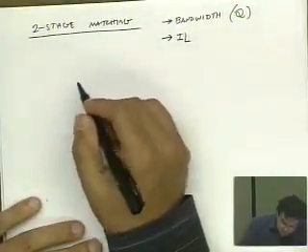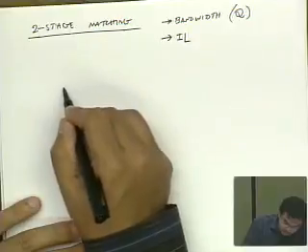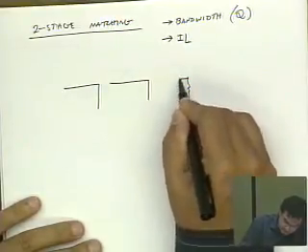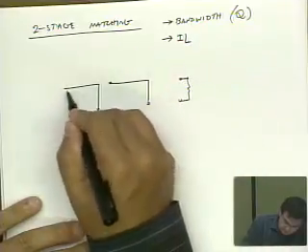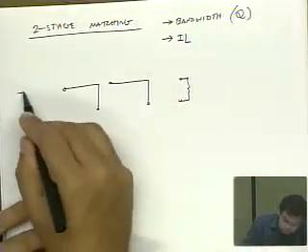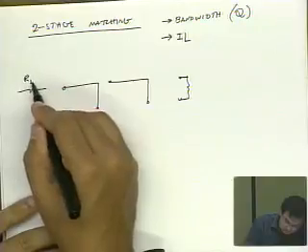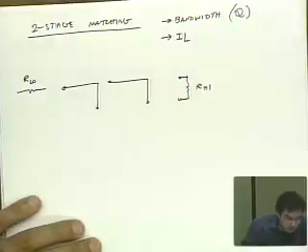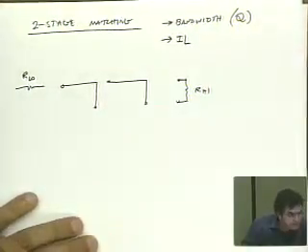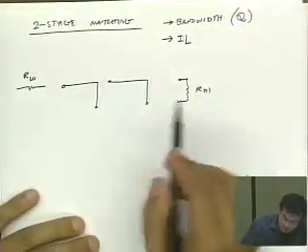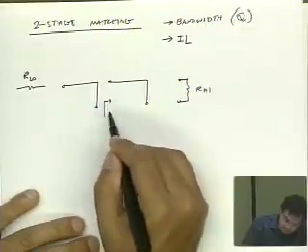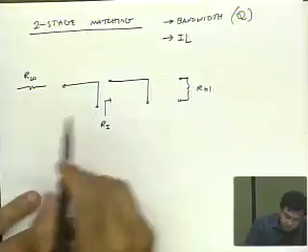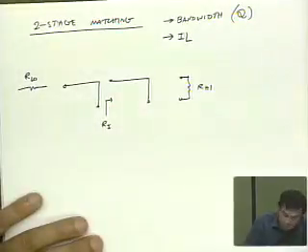Let's talk about two back-to-back L sections. So let's say that I have two L matching networks like this. So this is R high, and what I do is I can just analyze this as two cascade L matching networks, right? So in step 1, I bring this to some R intermediate, and then in step 2 I bring it to R low.